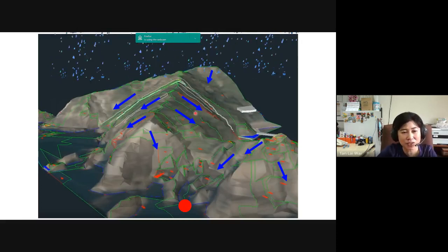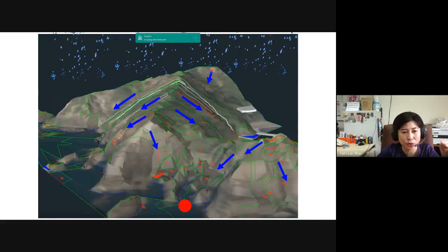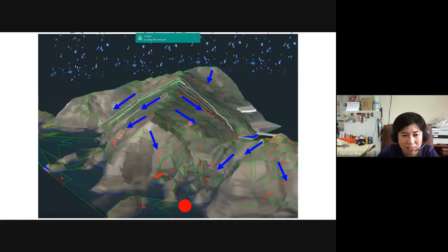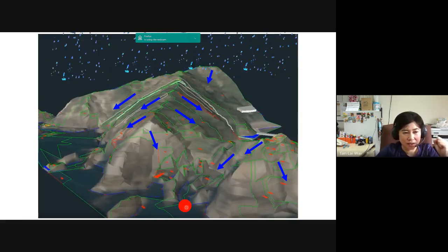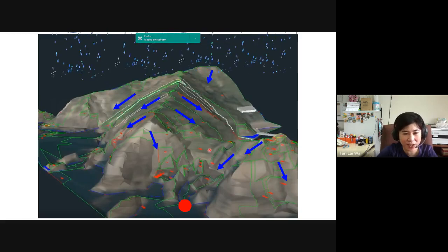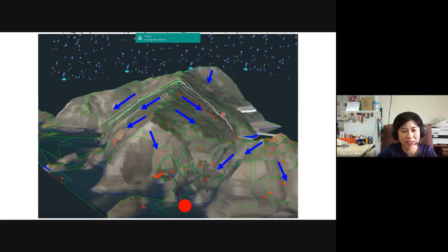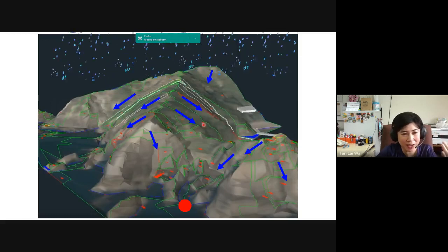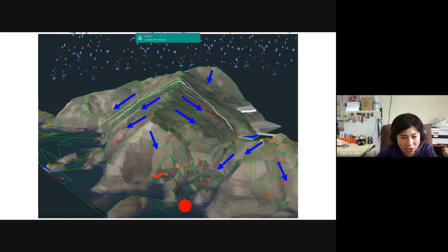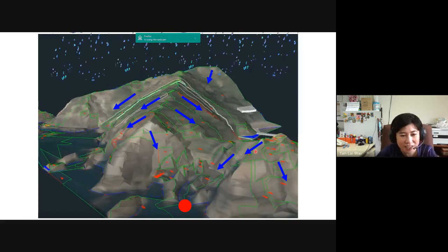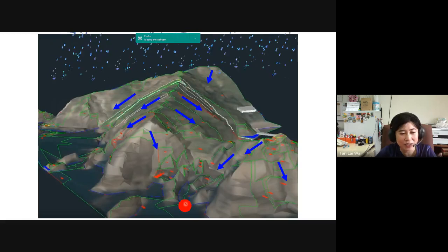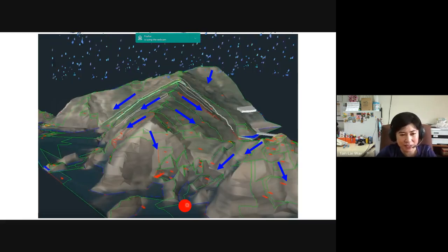You have rainfall intensity times the area, and you get how much discharge from the rain. That is why you use this rational method. That means you have I times A. A is the area that will be draining, that's why the term drainage area, the area that will be draining out of this outlet here.